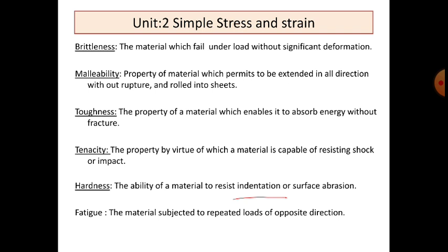In which type of loading does this condition come? When you are applying wind load to a building or structure, where the body is moving to and fro, cyclic flow is there due to the pressure of wind. The structure is moving to and fro. That type of loading is called fatigue loading.